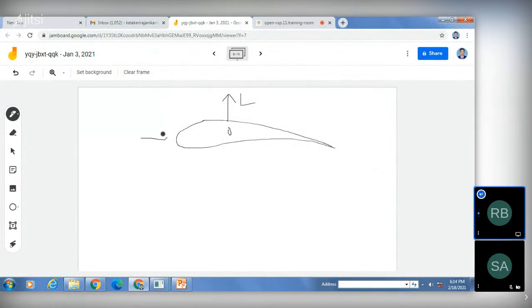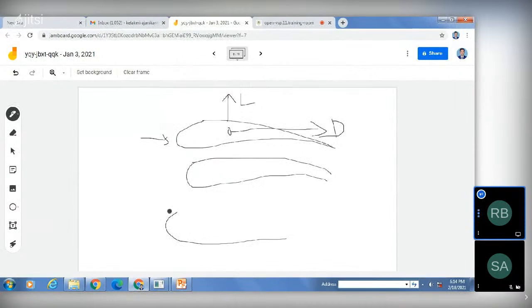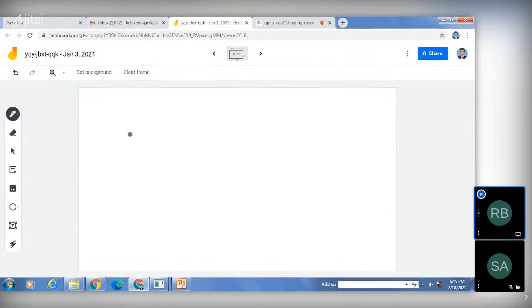And because of the air, we get one more component, that is the drag component D. So here we will make alterations in our aerofoil. If we take a symmetrical aerofoil, then we will not get that much pressure difference, which means the resultant lift will not be as much as compared to the unsymmetrical. So that's why we prefer unsymmetrical, just to increase the lift coefficient CL.